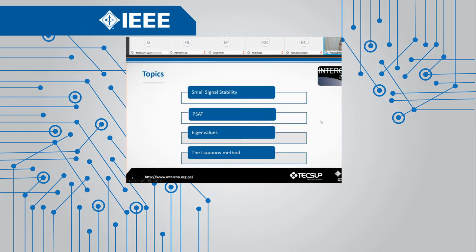Well, topics. There are four essential definitions that you should know: small signal stability, PSAT, eigenvalues, and the Lyapunov method. Small signal stability is defined as the ability of a power system to maintain synchronism when subject to small disturbances. PSAT is a toolbox from MATLAB for the analysis and control of power systems. Eigenvalues are the roots obtained from the characteristic equation of the state matrix. The Lyapunov method is a method which allows us to determine the stability of a system depending on the eigenvalues.